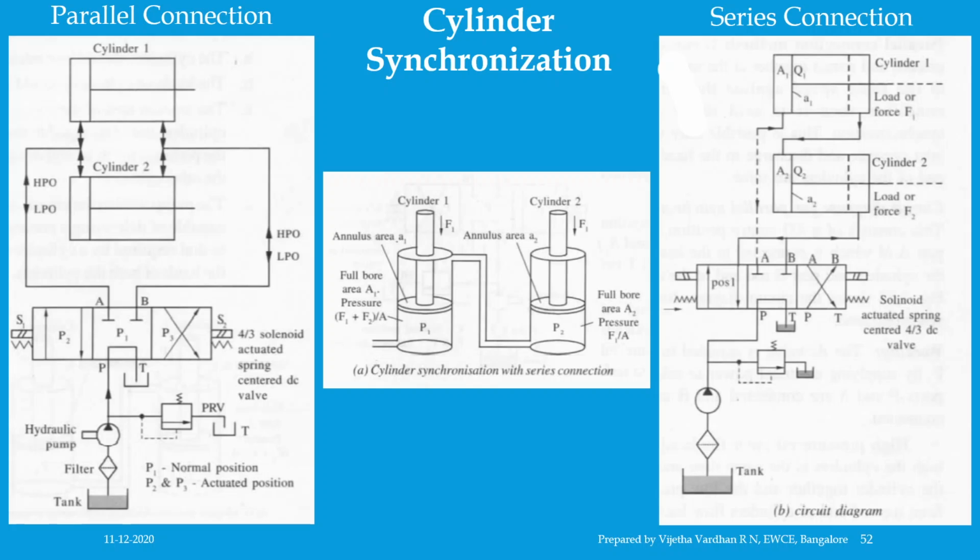Cylinders in parallel will not be possible to operate in synchronization using a common directional control valve, because oil takes the path of least resistance and the cylinder with lesser load extends faster. Synchronization is possible only if some form of mechanical devices is adopted.